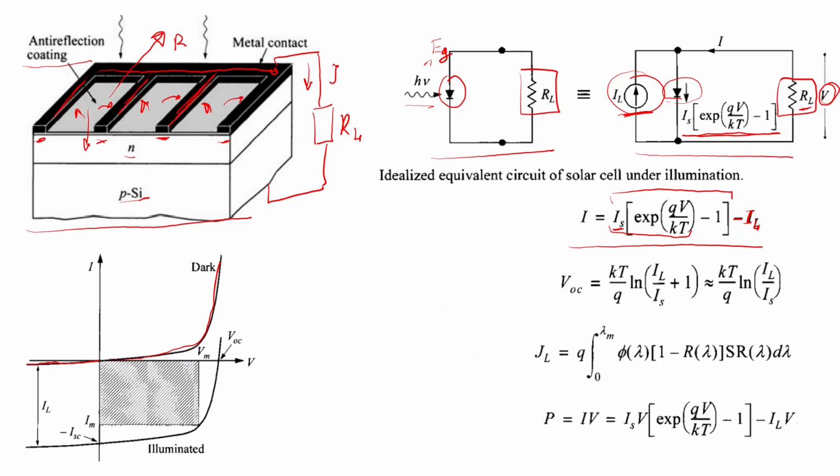So that is the drift current of minority charge carriers, the equilibrium minority charge carriers which we have in the dark. We actually reduce the concentration of equilibrium charge carriers next to the depletion region edges because of extraction.